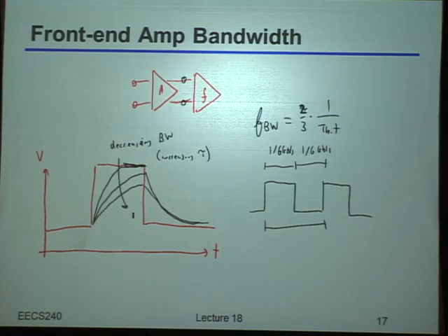So your question may be related to you're saying, well, look, if I don't really know exactly where I'm sampling, then I might actually have to settle more accurately, because otherwise I'll pick up more input-referred noise. That's a somewhat more complex topic in the sense of, to really answer that question, you need to know, first, where it is you're really going to be doing the sampling. And second, perhaps more importantly, what's the sort of probability distribution of where you're going to be doing the sampling, meaning how much jitter you actually have.